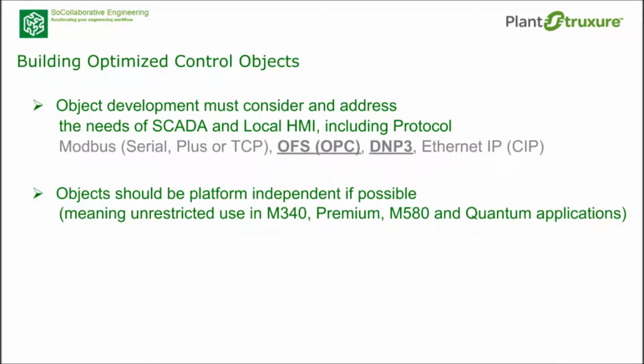Object development must consider and address the needs of SCADA and local HMIs, including the protocol that will be used for communications between Vijeo Cytec and the Modicon Unity controllers. U2V is optimized for the OFS OPC and DMPR drivers of Vijeo Cytec. Objects should be platform independent if possible, meaning unrestricted use in M340, Premium, M580, and Quantum applications.